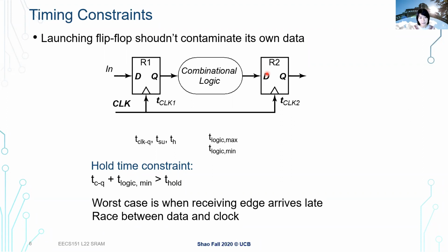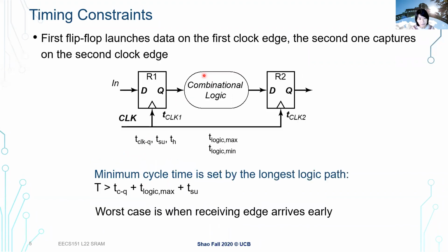One thing you notice here is that this is purely internal to your circuit, right? It's about your clock-to-Q delay and the complexity of your combinational logic. If you think about the setup time constraint, our clock period needs to be longer to satisfy it. So if we run into a setup time violation, we can always just slow down the clock. That's always one easy thing to do to make sure your circuit is still functional.